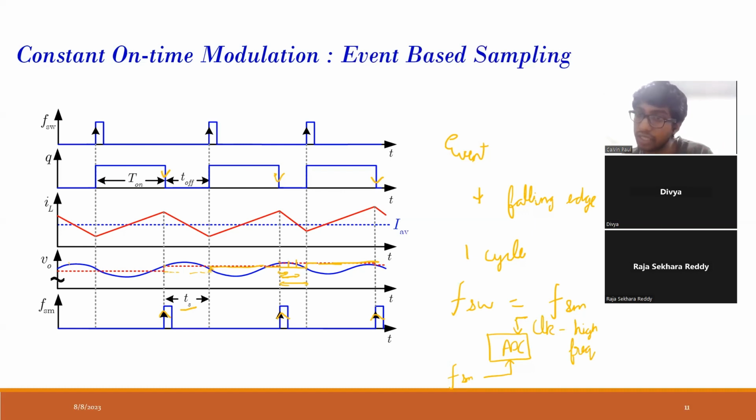This is the internal cycle of your ADC chip or the actual ADC device. Based on that clock, it determines how much time it takes for one cycle of the ADC operation. So let us say for one particular ADC, it takes around 12 cycles to convert the sample value to a digital value. So that will decide your delay.